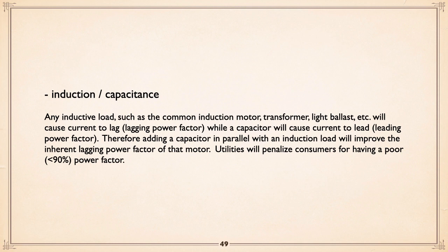Well, how do we get around it? By having a capacitor in parallel with the induction motor. The capacitor tends to want to lead, the motor tends to want to lag, so you can bring it back up to within that 90% power factor. Okay. Now, how do I size these?